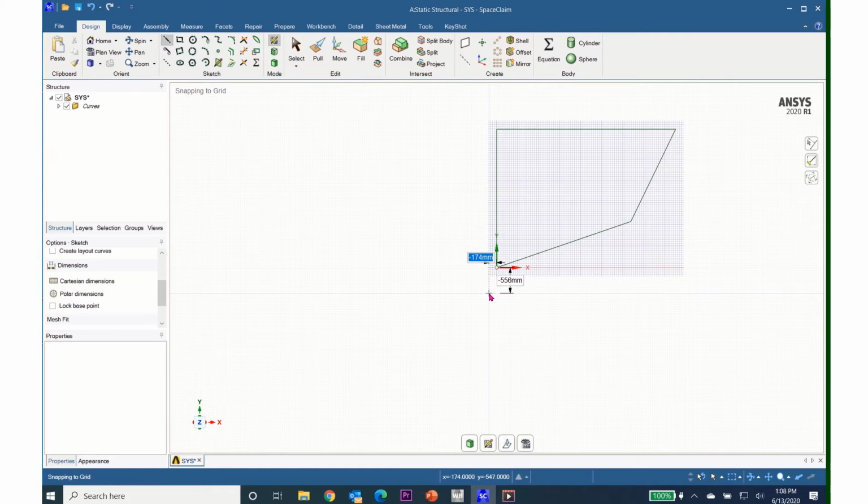Now I have all my outside lines. I have one internal line to draw, so I can press escape so that I don't draw the line from the origin. I still have my plus sign indicating that I'm drawing lines. I hover over the intersection until I see the sphere, and then I click on that and I can drag my line down to this intersection sphere, and when I see the sphere I can let go, and I now have my truss, all the members of my truss put together.